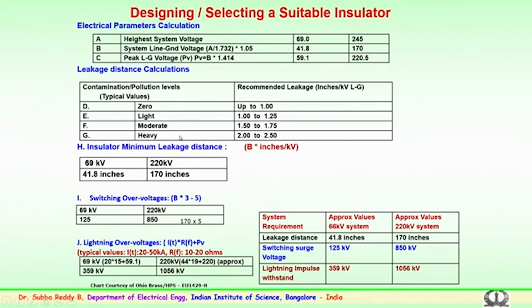So, for transmission lines passing through different zones, while calculating the leakage distance we have to bear in mind the factors to be considered. In case your transmission tower is running near a moderate pollution zone area, a factor of 1.5 to 1.7 is considered. Similarly, if it is high, 2 to 2.8 is considered.